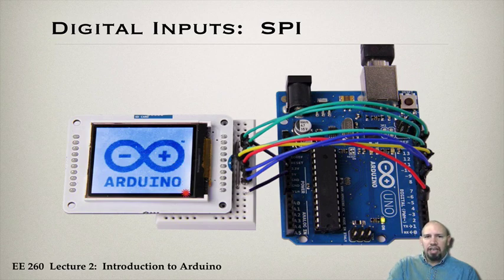The intensity is sent. So, for example, if this were a color LCD, each pixel has 3 color elements: red, green, and blue. Each of those colors has associated with it a number that tells it the intensity. So red would have 8 bits that would describe the intensity. 255 would mean full intensity, 0 would mean zero red. So every pixel would have a value for red, green, and blue. And so 8 bits for red, 8 bits for blue, 8 bits for green. That's 24 bits that need to be sent for each pixel in this image.